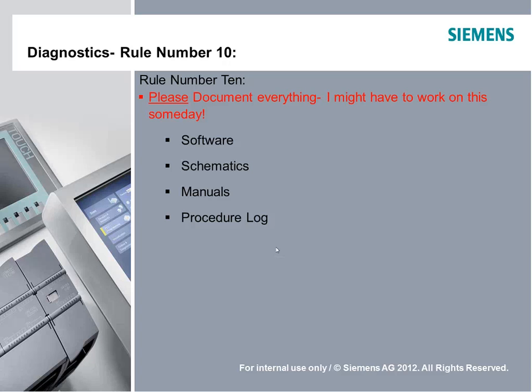Localize the problem is number 5. Don't look at a machine as this gigantic monstrosity and think, how can I possibly fix this. Machines are designed in subsystems. So typically if you've got a big machine, you're going to have an HMI system, maybe a temperature controller, and maybe a motion controller. And if the software was written well, then it is going to differentiate and have different structures for each one of those subunits. But if you can focus in on what you think might be the cause rather than looking at the overall picture, things become a lot more clear.